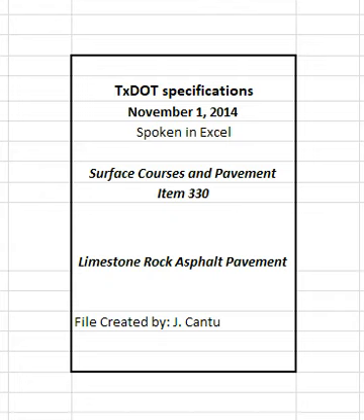2. Materials. 2.1 LRA mixture. Furnish LRA according to DMS 9210, limestone rock asphalt, LRA, of the type, grade, and surface aggregate classification, SAC, shown on the plans. 2.2 TAC code. Furnish CSS1H, SS1H, or a performance-graded, PG, binder with a minimum high-temperature grade of PG58 for TAC code binder in accordance with Item 300, asphalts, oils, and emulsions, unless otherwise shown on the plans or approved.